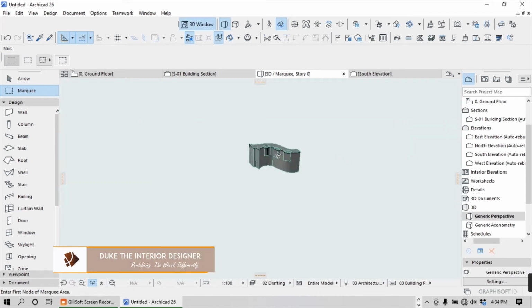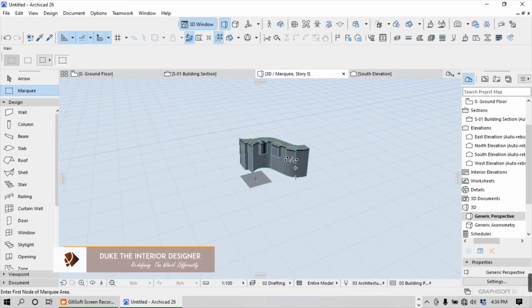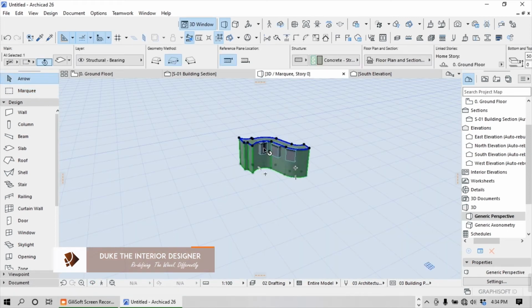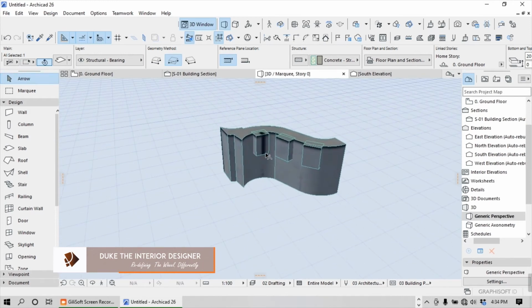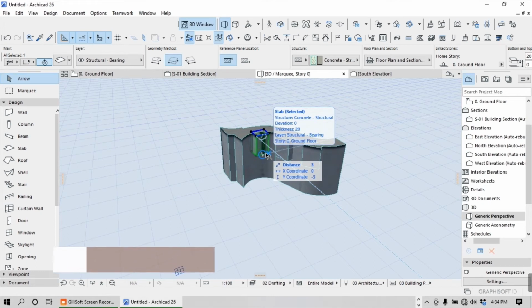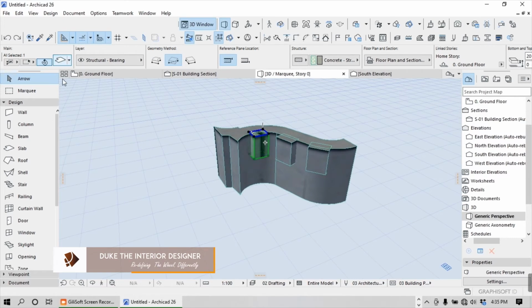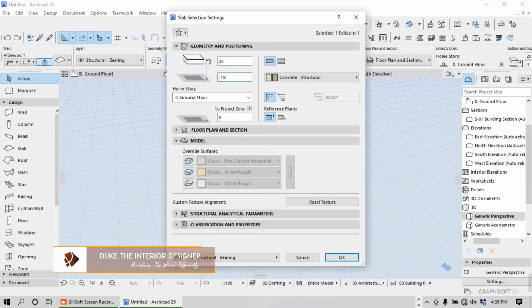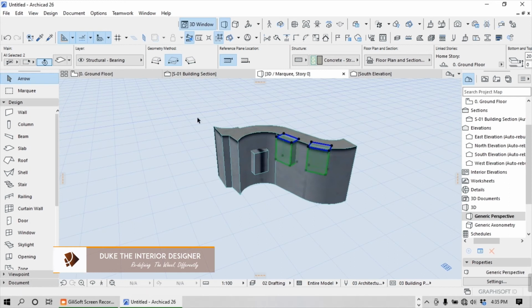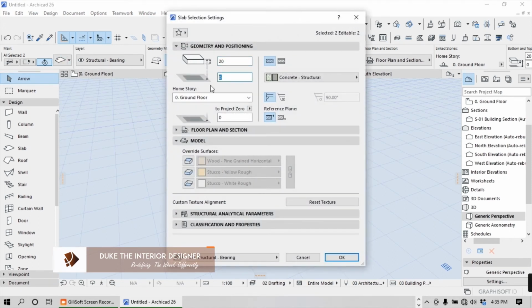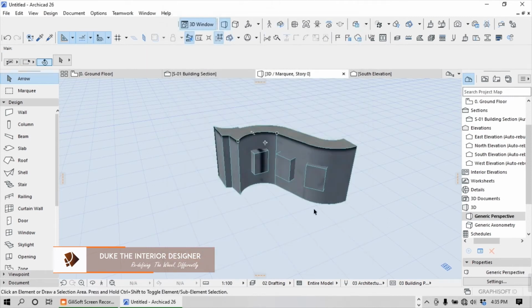Let's make sure that these are pressed in the mid. The big item is 50 and this is 20. So where would be the mid? That means you need to offset this by 50 minus 20. That makes it 30. Divide into 2, 15. Offset by 15, and you do a negative because you're going downwards. So for all of them, do negative 15. So that's the design that we have.